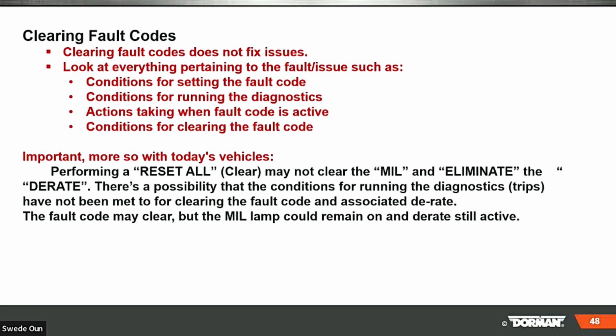I am slowing down on this slide. Look at everything pertaining to a fault issue: conditions for setting the code, running the diagnostics, action taken when the fault code is active, conditions for clearing the fault code. Important, more so with today's vehicles, performing a reset that cleared may not clear the MIL and eliminate the derate. And you guys that work on this stuff, you know that actually is happening.